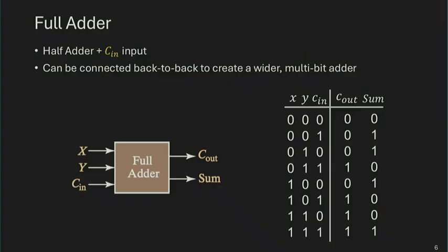Right. So this full adder works as follows. You have 3-bit inputs. X, Y are your data, the 2 input operands. And then C is the carry from the previous bit. And then based on these 3 inputs, I'm going to do an accumulation of these 3 bits to produce a sum and produce a carry. Right? And we can look at its behavior from the truth table. If all of the inputs are zeros, you're just taking the accumulation of these 3 numbers, you get 0, 0.